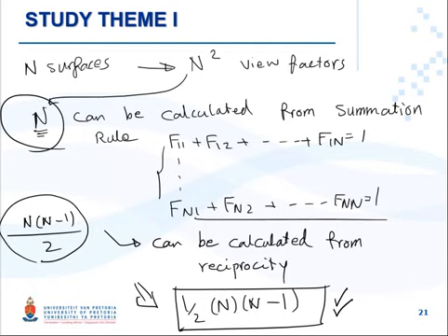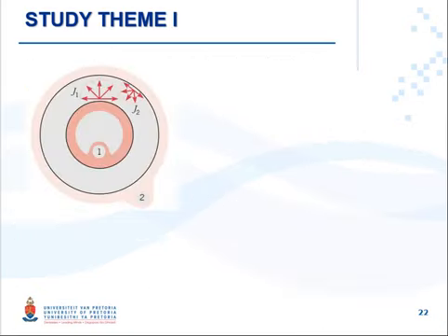But how can we find them? Either from standard geometries in tables or pictures, or by using the self-view factors.